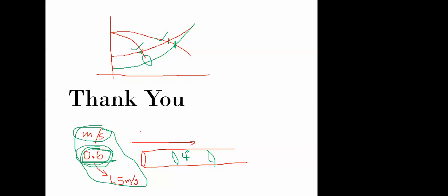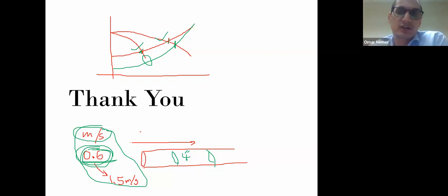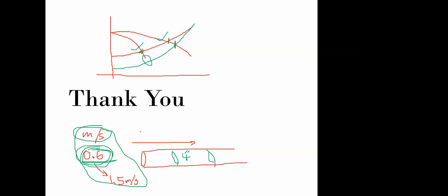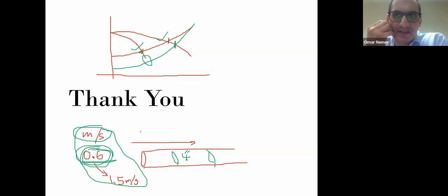Mr. Omar, regarding the text, does the non-clog type need a submersible pump? In case this one is not covered, it is covered in the non-clog type. We can also use this vortex type. Yes, it's like an option. You can use non-clog, you can use vortex. It's okay. But the efficiency is the major difference. Non-clogs are better.